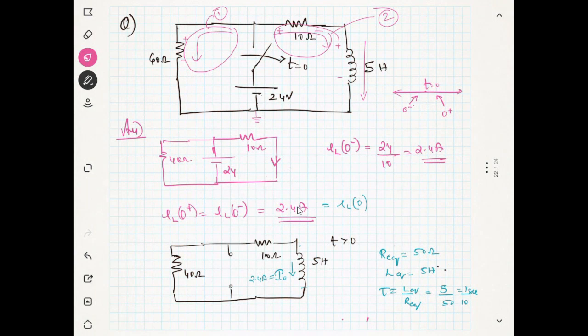There is no first current or second current now. Now there is only one current, right? Because the center part of the circuit is now an open circuit. So what will happen? The polarity of the voltage across the resistance will now change. It becomes plus and minus. If it becomes plus and minus, then what will happen? The inductor voltage also should change in the same way, right?